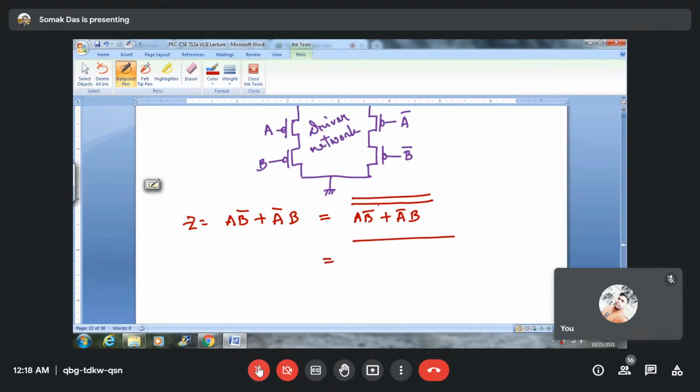So this lower bar, just break this, use De Morgan, then what it becomes? AB bar, whole bar, and this sign will change. A bar B, whole double bar. Again, further reduction. So again, you can break this line and change the sign below. That is what De Morgan says. A bar plus B double bar.